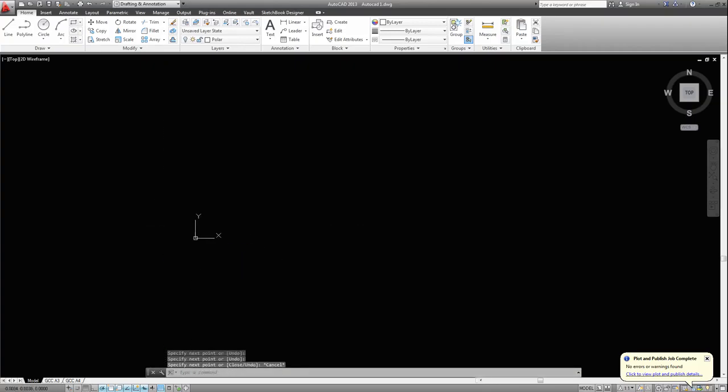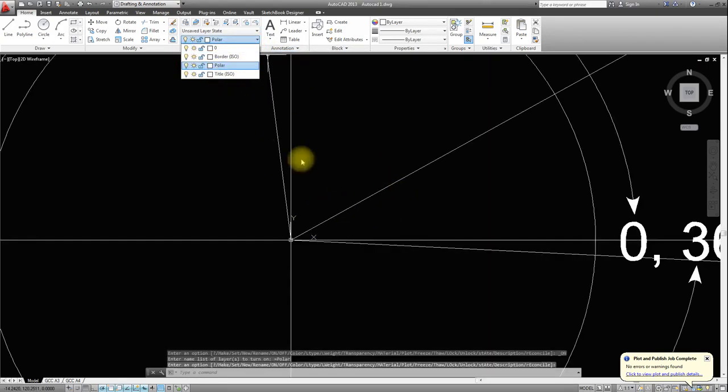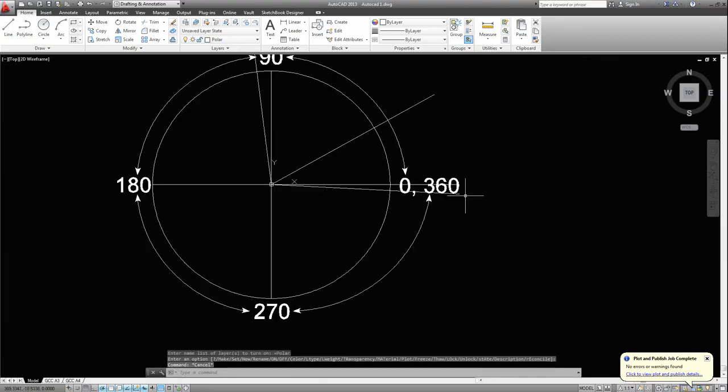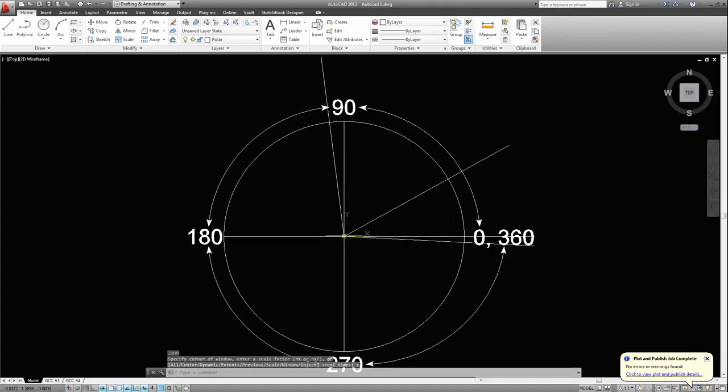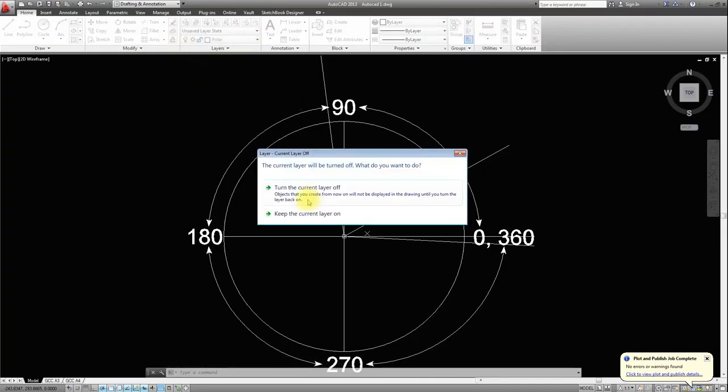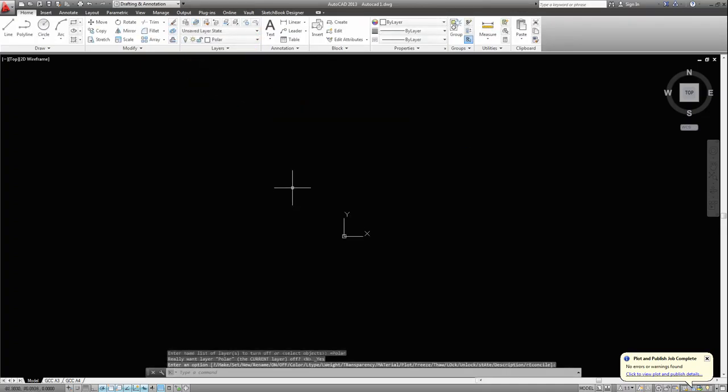That's our line. If you want to zoom in, why that's going in there is because we know that that geometry is still there. AutoCAD still knows where it is. Just because we've hidden it, it doesn't mean it's gone away. So what happens is when we zoom extents, it's leaving it in the middle of the screen. Even when I turn that off, the zoom extent still knows that the drawing is there. If I didn't have that, this would zoom over to the bottom right hand corner.